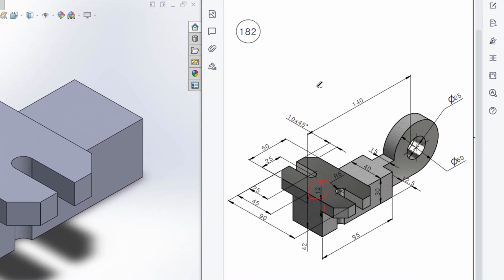In our sketch we can see that we have a circular profile, and this outer circular profile has a dimension of 60 diameter, and this circular profile has a distance of 140 unit. And after drawing the circular profile from this lower face, I will draw a center line here. I'll draw a line and tangent this circle to this line. Okay, after that I will draw another line here along the midline. Then I will trim this unnecessary line, and I'll close this shape.